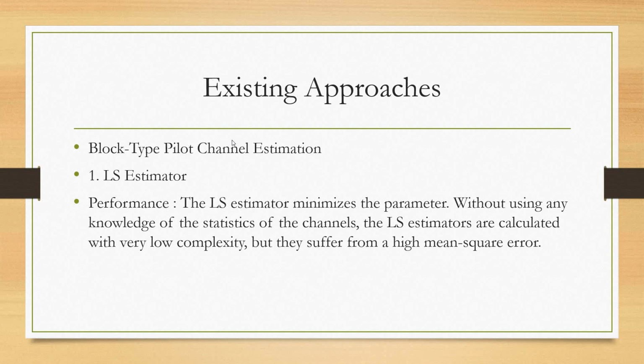There are several existing approaches. The first one is block-type pilot channel estimation. The performance of the LS estimator is that it minimizes the parameter without using any knowledge of the statistics of the channels. The LS estimators are calculated with very low complexity, but they suffer from a high mean square error.